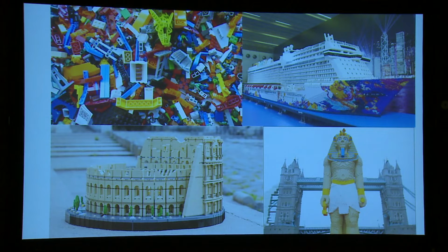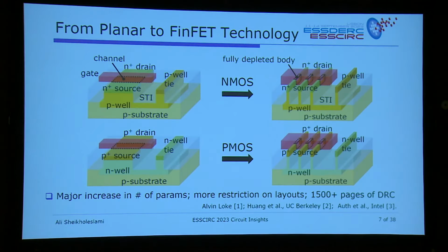Believe it or not, the same story goes for our circuit design. We used to have just the CMOS transistor. It was 0.8 micron technology. You make an amplifier, 2 transistors, you write all the equations, you derive everything from beginning to the end, you analyze it, you measure it, everything would work. But then came, well, maybe thresholds shouldn't be just one value, the standard. You should have low threshold, high threshold transistor, then ultra low, and then ultra high threshold.